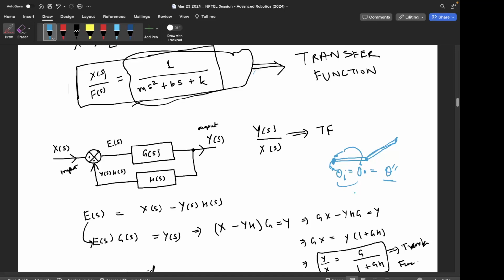If you are splitting that also, then you would say that's just open loop: you are sending some velocity value that is converted into some current value, and that current is applied. But in many of these motors, there will already be an inbuilt circuit which does that closed loop thing. So from a practical point of view, the stepper motor is maybe the most common way in which you would do open loop control.